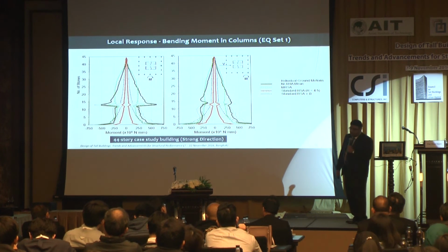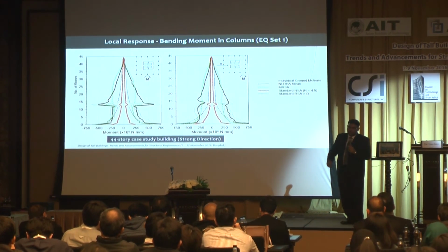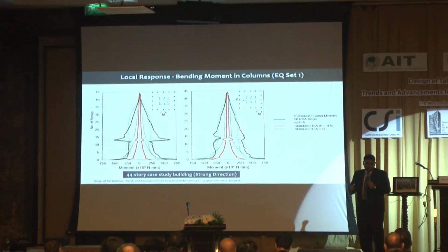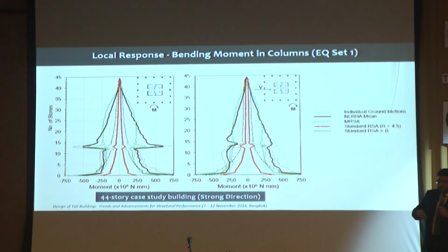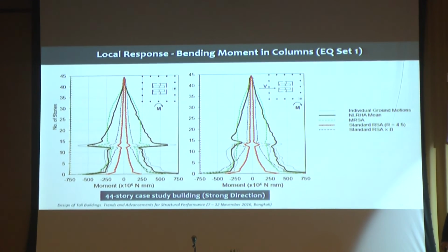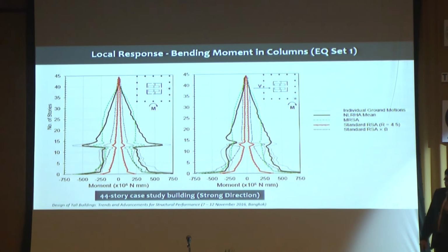Local response is a kind of challenge because obviously we have to delay the structure's time period, and local response is sensitive to how we delay that time period. One way was to apply the stiffness modifier, just like the ACI 318 recommendation, throughout the building's structural members which are expected to crack. We first tried this idea, and we are still in the process of getting a smarter conversion which can help us get more accurate estimations of local response as well.